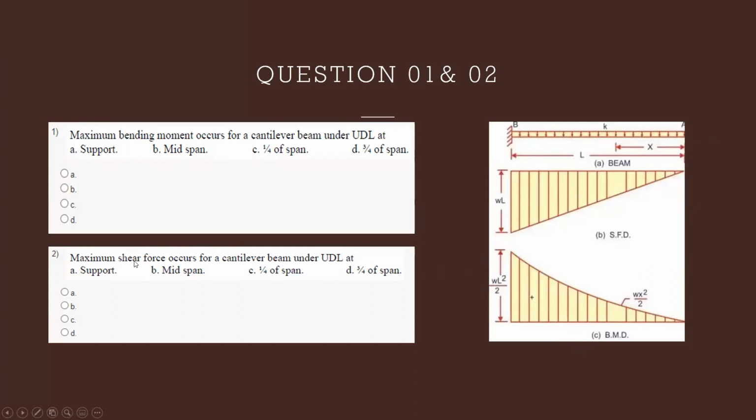And the second question is related to the shear force. Same, if we see this shear force diagram, SFD, of the cantilever subject to a UDL, we can see that the shear force diagram has a maximum ordinate at the support of WL.